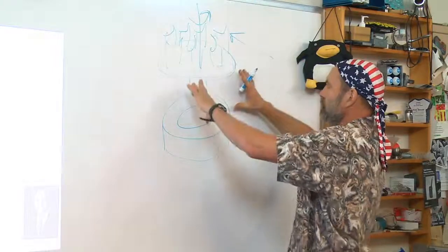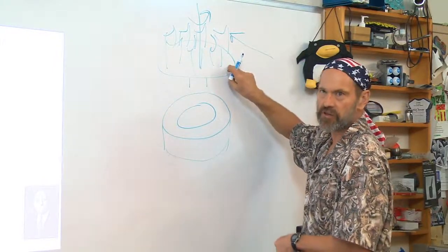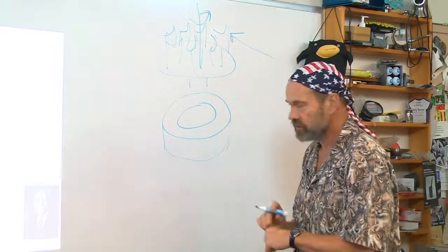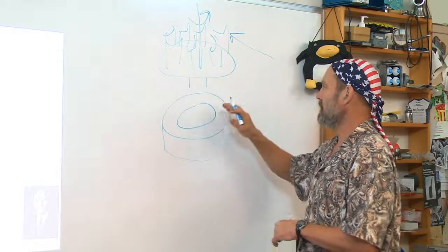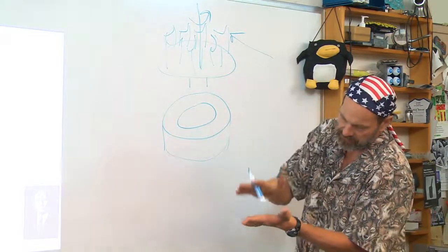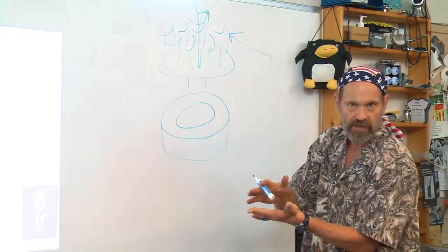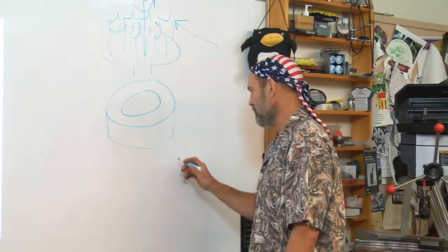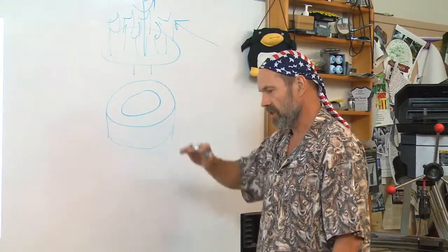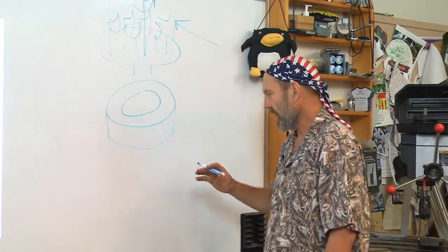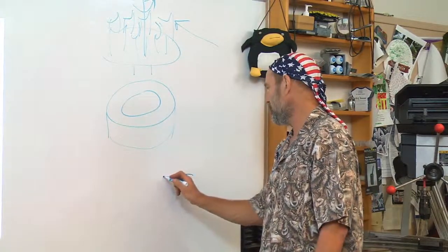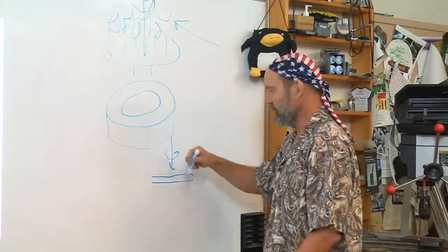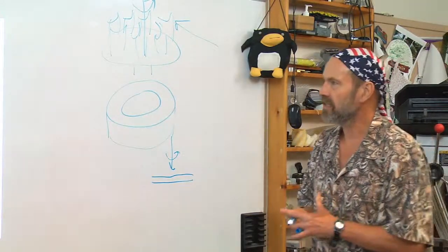There's a huge thrust load from the weight of the structure, and in some turbines, axial flow turbines, you would have huge axial loads. Well, to make two plates perfectly flat that'll fit together and not have a high point somewhere such that you can have a hydrodynamic bearing is very difficult. It's also very difficult to imagine that if I want to resist a very high thrust load, how do I do that between this surface and this surface when I'm pushing down and spinning? Where does the hydrodynamic wedge build up, like we showed in this picture?